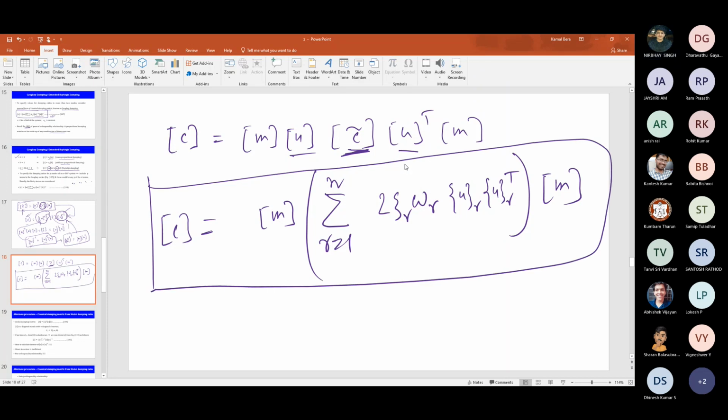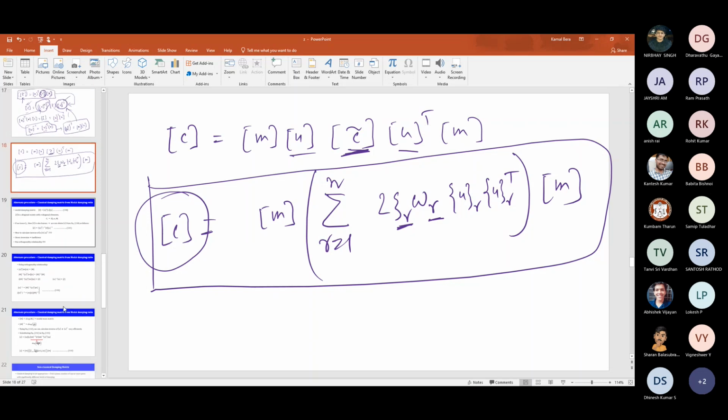Now we'll go through one problem and then it will be more clear to you. Let's say I've given you two modes. So you know the modal damping ratio of the two modes, that is for, let's say, the first mode and the third mode. So omega 1 zeta 1 you know, and omega 3 zeta 3 you know. Put it here for this matrix. Also use the Rayleigh method, finding out alpha and beta, and check whether you are getting the same result or not. Very interesting, right?